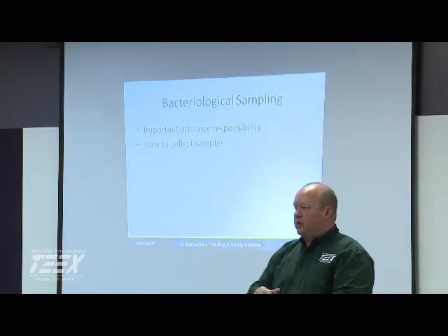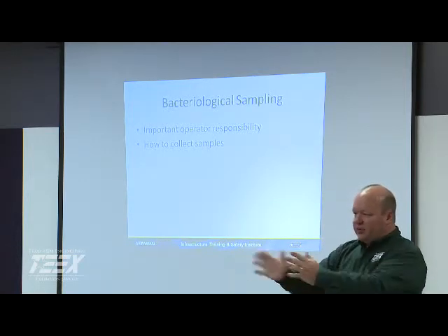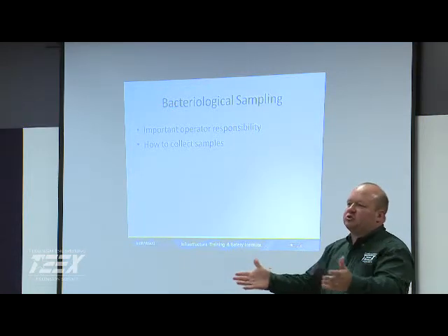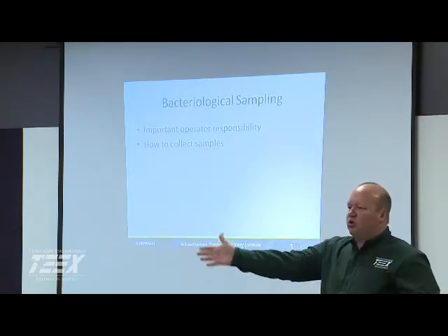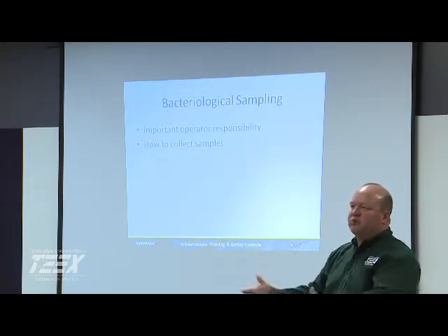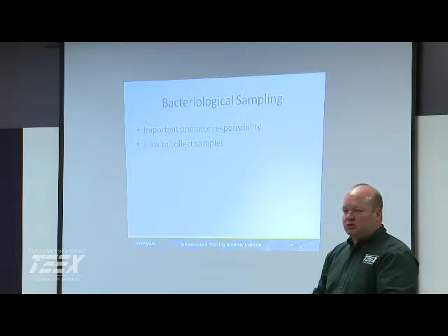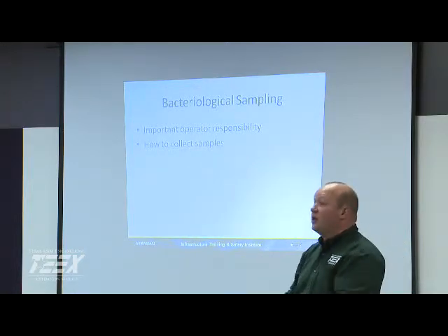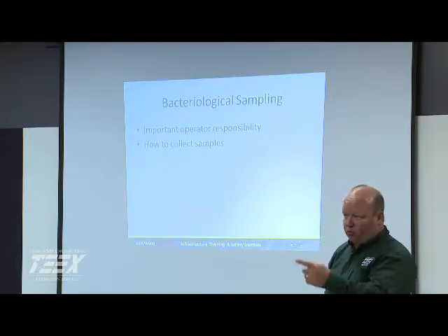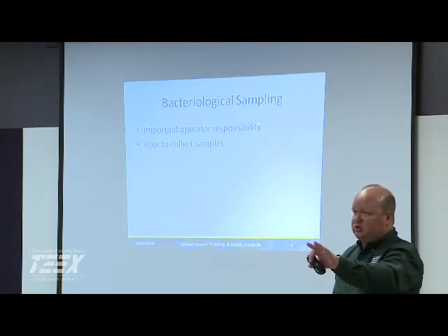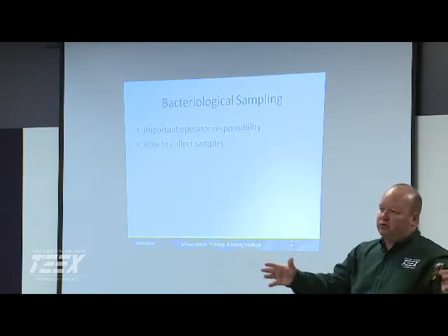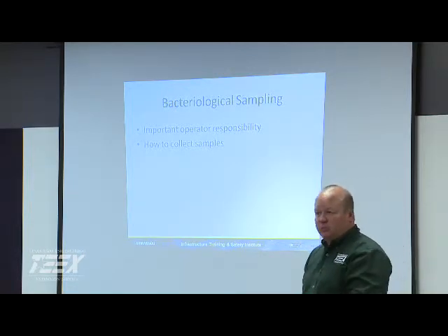We had Arizona, they had a sampling site, and we'll get into sampling plans and site sampling, but here's this house, and the house has been vacant for how long? They just did work on the pipe in the yard, and they're out there pulling the sample from that. Well, obviously, there are several things wrong with that sample site now. So you need to have alternative sample sites. You need to know when it is a good time to do something at a different location. It can be as simple as some wording, where you have an address and you say in the vicinity of. So if you take it next door, upstream, downstream by a house or two, you're still getting a good representative sample.